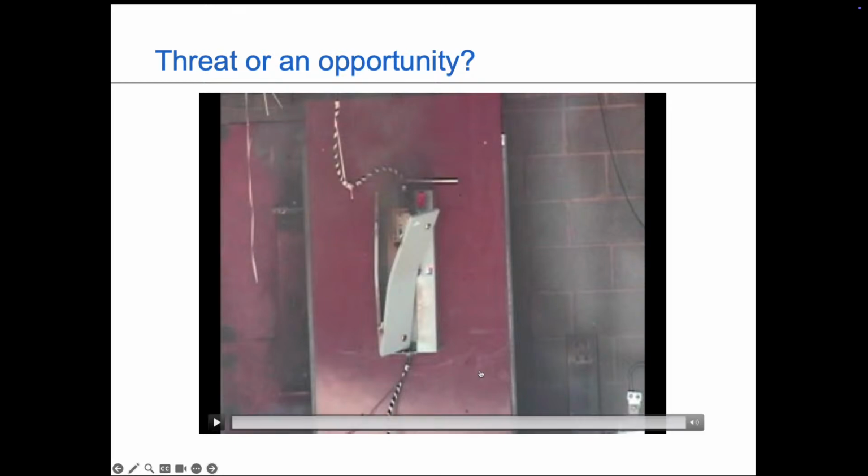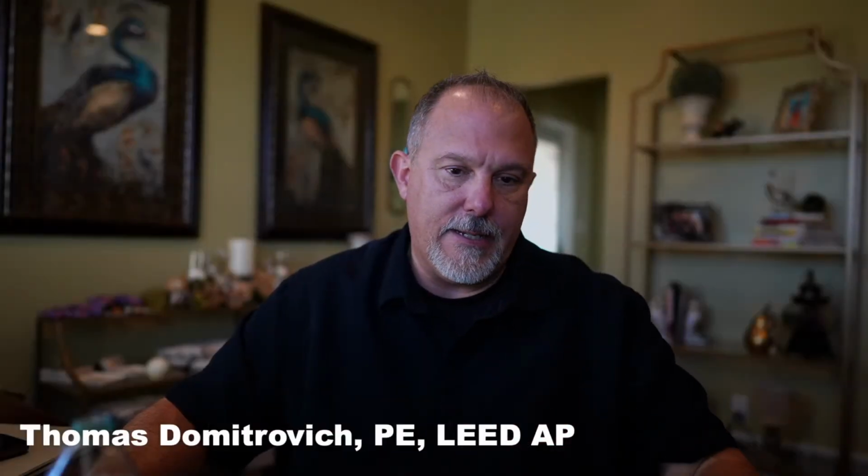So that is an example. That's an example of exceeding the short circuit current rating of a piece of equipment. The fault wasn't inside the equipment. The fault was outside the equipment, and the components that are inside can't hold it together under the stresses that are presented or placed upon the equipment because of the available fault current. All right.